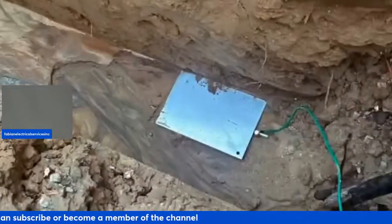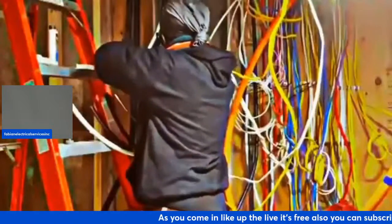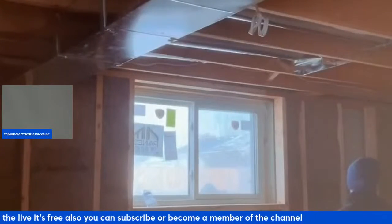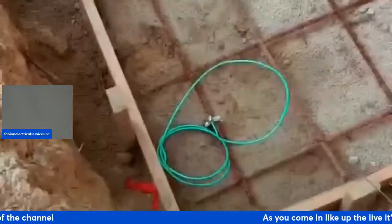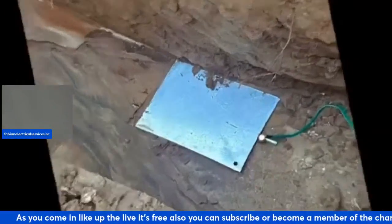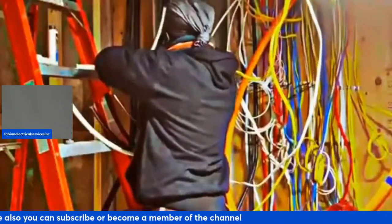And again, why GFCI outlets are important. They prevent electrocution and severe electrical shocks by quickly interrupting the flow of electricity. Again, they can also prevent fires and reduce the severity of fires by interrupting the current during a ground fault. They are crucial safety features in areas where electrical devices are used near water, such as kitchens, bathrooms, laundry rooms, garages, and outdoors. Again, outdoors, you're going to find them protecting the outdoor circuit.